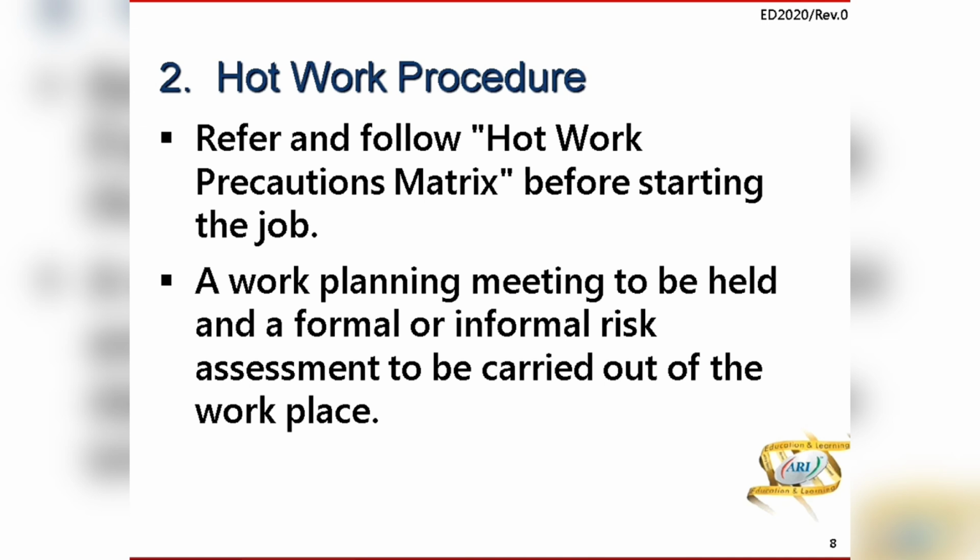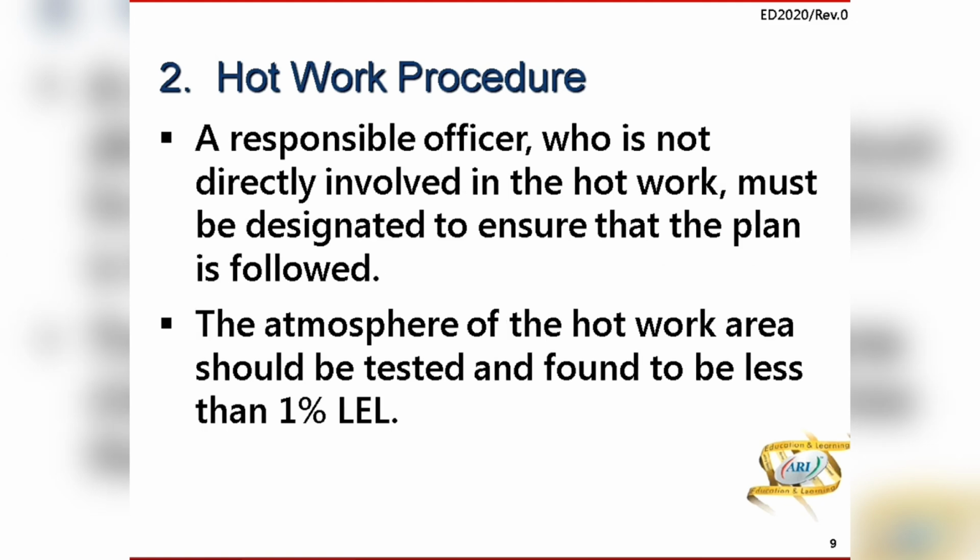So refer to your hot work precaution matrix before starting the job. A work planning meeting should be held and a formal or informal risk assessment carried out at the workplace. A responsible officer who is not directly involved in hot work must be designated to ensure that the plan is followed. The atmosphere of the hot work area should be tested and should be found to be less than 1% LEL.